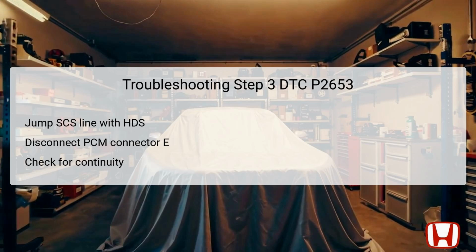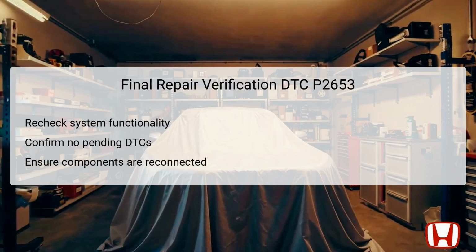To move forward with resolving DTC P2653, after all necessary repairs are conducted, it is vital to conduct a final repair verification to ensure the issue has been successfully resolved. This involves rechecking the entire system's functionality to confirm that the rocker arm oil control solenoid operates according to specifications. The technician should utilize the HDS to verify that no pending or confirmed DTCs are present following the repairs. This step is crucial, as it validates that the previous electrical faults have been addressed and rectified.